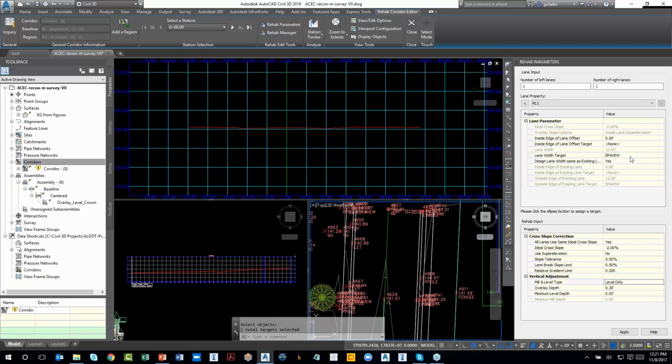Sometimes your existing edge of pavements may not be the same as your finished grade edge of pavements you wanted to be. Maybe your existing edge of pavements are crooked, therefore sampling existing slopes from your center line to the existing edge of pavement, or even the existing edge of pavement survey figure may be inaccurate. So you wanted to offset that existing edge inside, and you wanted to deviate. Or if they are crooked, maybe you wanted to have a fixed with the existing finished grade design edges. Or maybe you wanted to design your finished grade edges and rehook them up, right?